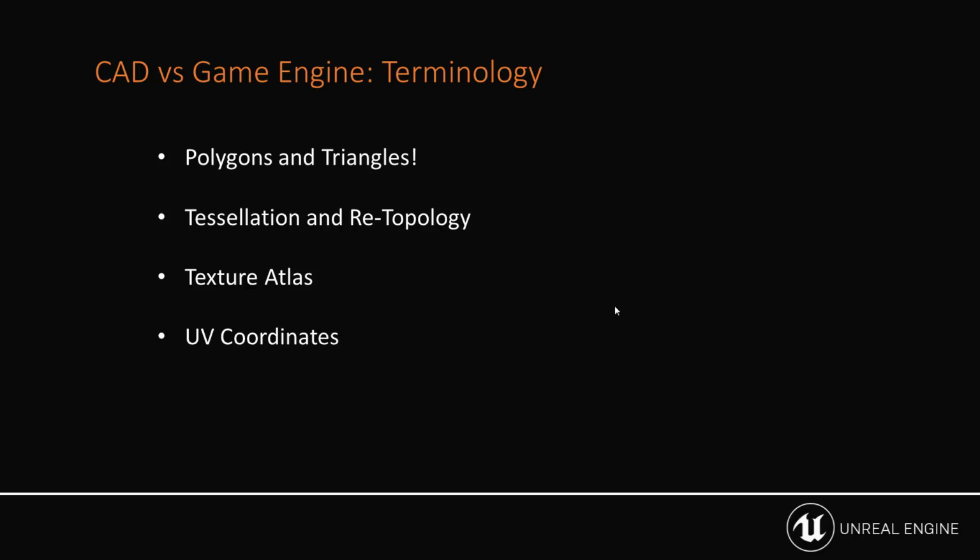Now, of course, to get those textures, we need, again, UV coordinates. And UV coordinates are essentially the coordinates that allow for textures to be placed on those polygons or on those triangles so that they will display correctly in your renderer of choice, in this case Unreal Engine. So once the UVs are provided and they're placed properly and clean, things like logos and details from different types of textures, tire details, whatever it may be on the rubber, if it requires a texture, UV coordinates are going to produce that accurate detail for you.